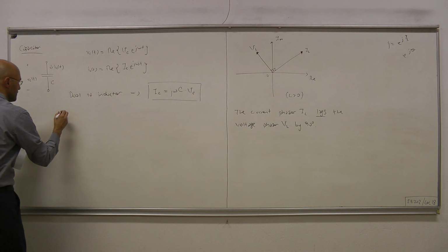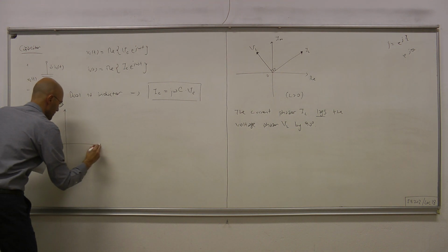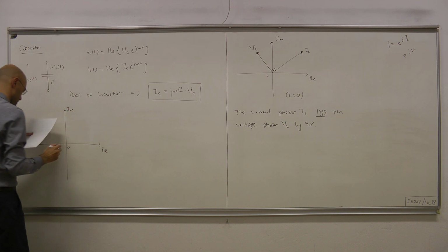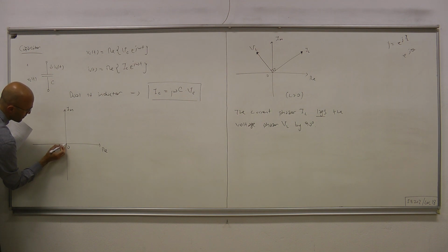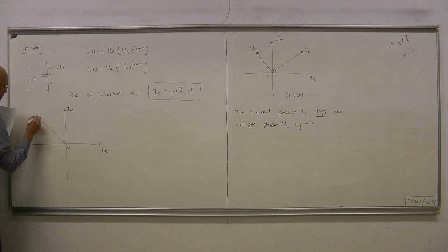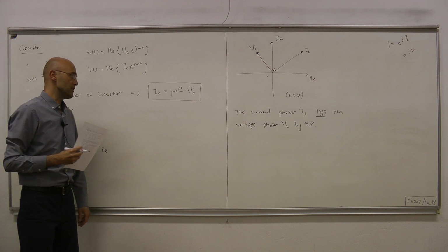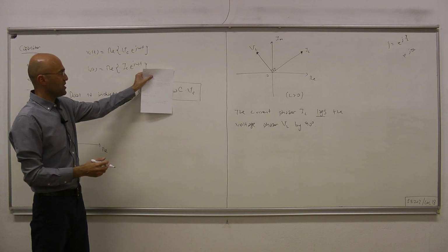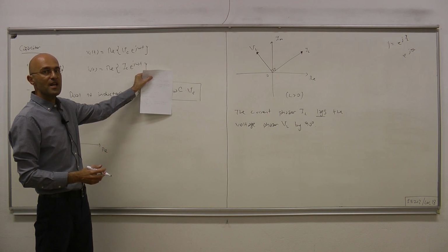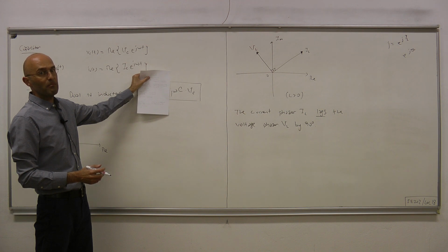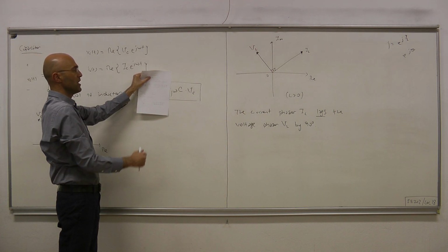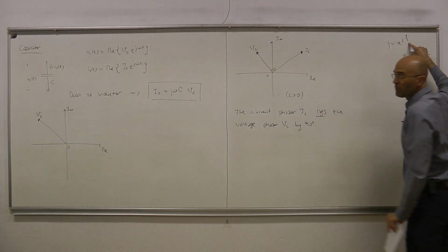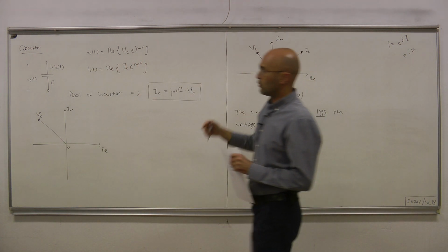Okay, and as for the phasor diagram, real, imaginary, zero, suppose that this is the phasor of the voltage, VC. Then IC is, first of all, magnitude of VC scaled by a factor of omega C, and then as for the phase, it's multiplied by j, so the whole thing is multiplied by j. So that means we're rotating the voltage by 90 degrees in the counterclockwise direction.